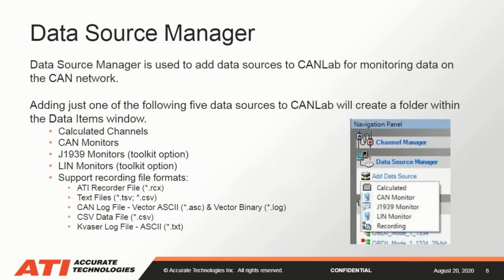The next manager below is called the Data Source Manager. And this is where we're going to add our calculated channels and our various monitors and our recordings. We support various level recordings from different utilities. So we support our own recorder file, obviously, text files, Vector ASCII file, CSV data files, and the standard Kvaser log file as well, the ASCII2.txt.